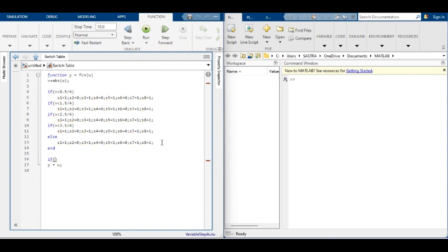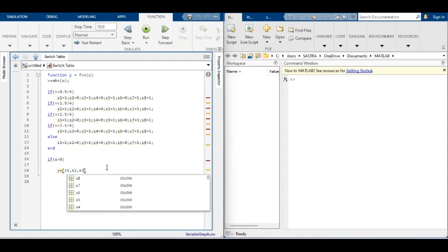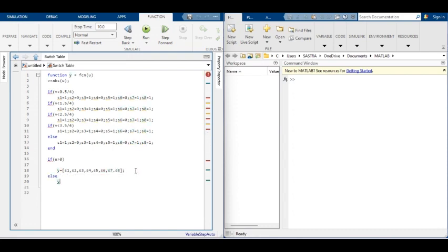The switching states are defined for the period of 0 to 90 degrees and from the 0th level to the 4th level, which is the first half of the sinusoidal reference. The remaining period from 90 degrees to 180 degrees is repeated utilizing comparison. To produce the negative half, the switch pairs are swapped. The symmetrical nature of the cascaded H-bridge produces the same 4 levels in the negative polarity.